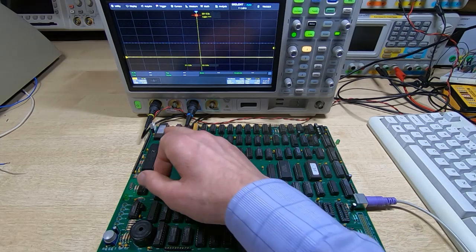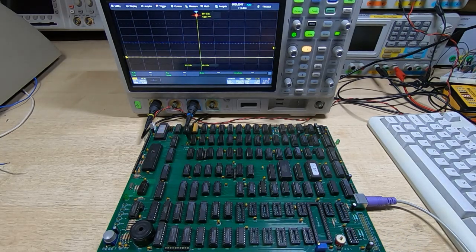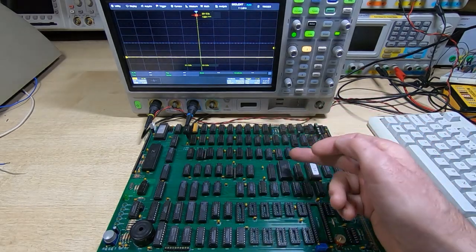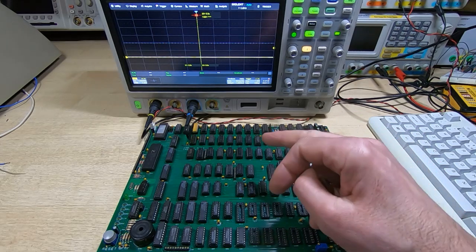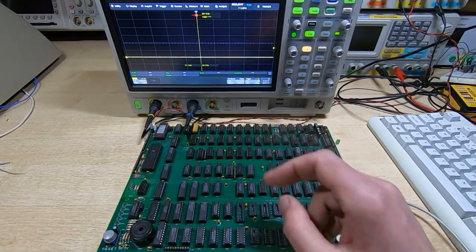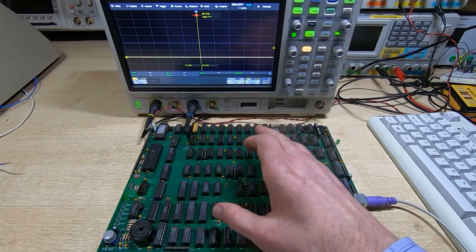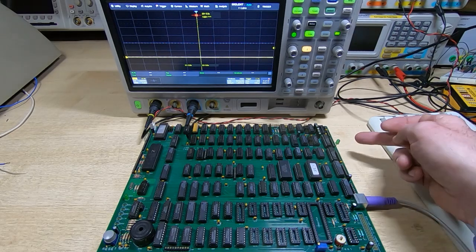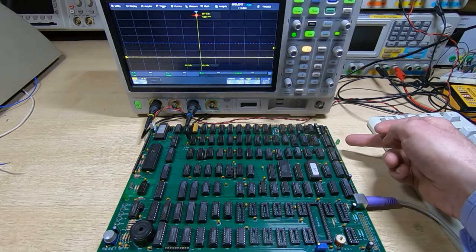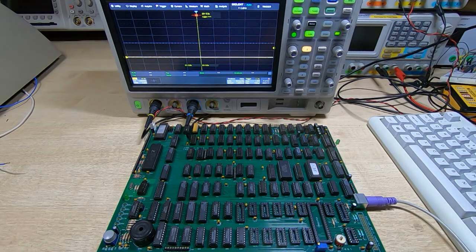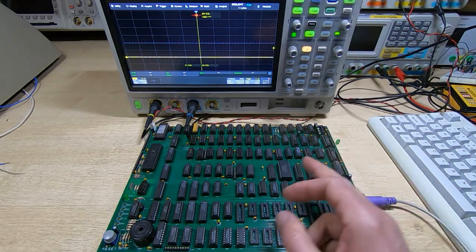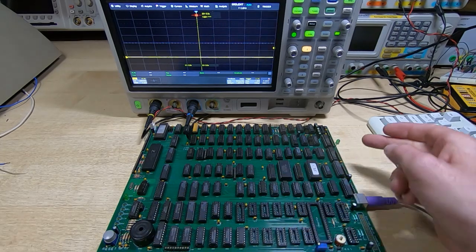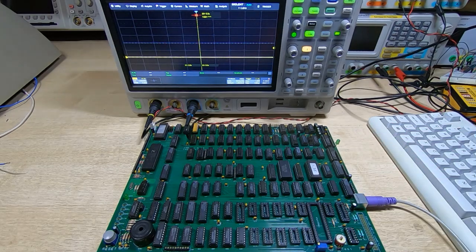And this ROM contains the self test that I described in an earlier video. So it tests the checksum for the ROM, it checks the SRAM, checks the bank 1 RAM, checks bank 0 RAM, does quite a lot of checking. Got all the DRAM devices fitted of course. Now when it's running the self test, this LED comes on, and it should come on, self test takes about 5 seconds. We're running the Z80 at 2.5 megahertz, so it's quite slow. But then what should happen is the LED should turn off.